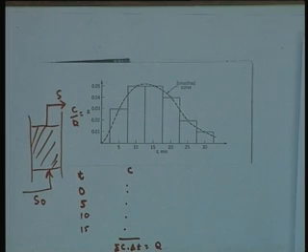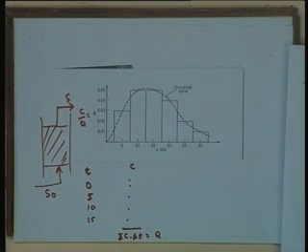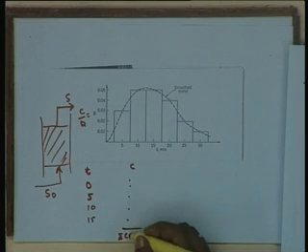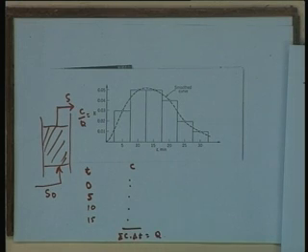If there is any absorption of some tracer into the system, or some reaction taking place, or if the tracer is not a good choice, that means it is participating in the reaction, in that case the total amount of tracer put into the reactor will not be equal to sigma C delta t, and obviously such an analysis is erroneous, which should not be accepted for determining the flow behavior.